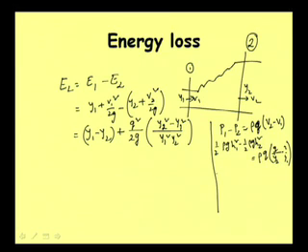Okay. Now this part we can write as rho will get cancelled, G will be going there, 2 we can write here, so we can write it as H1 square minus H2 square, this is equal to twice Q by G, and then this Q bringing out we can write Q square by G, and then that will be Y2 minus Y1 over Y1 Y2. Well, here we are using Y, so this H would be actually Y.